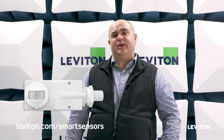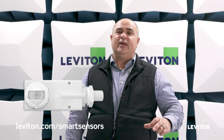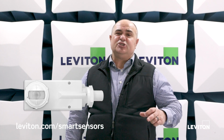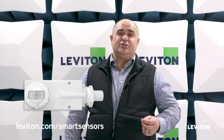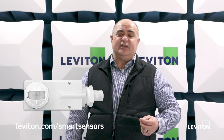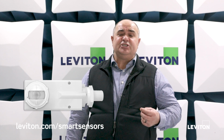You might say, well, John, what are some of those code requirements that we'd have for a warehouse? Well, one of the things for a given warehouse is that you have to be able to control the lights in a given aisleway as an independent zone of the other areas. One of the nice features of the fixture mounted sensor is that we can pair multiple sensors together.